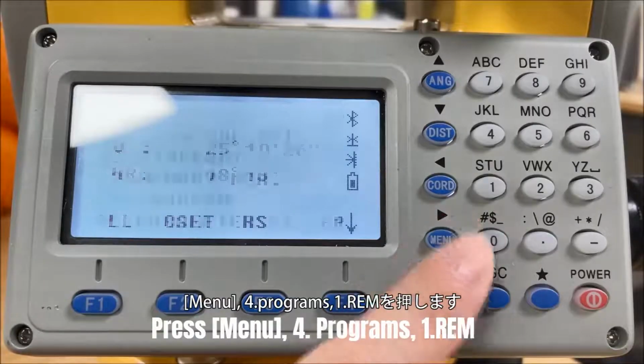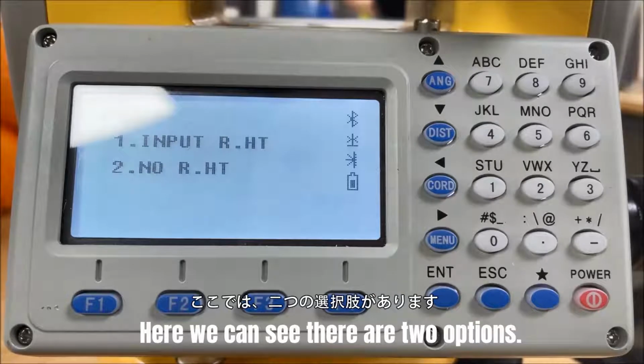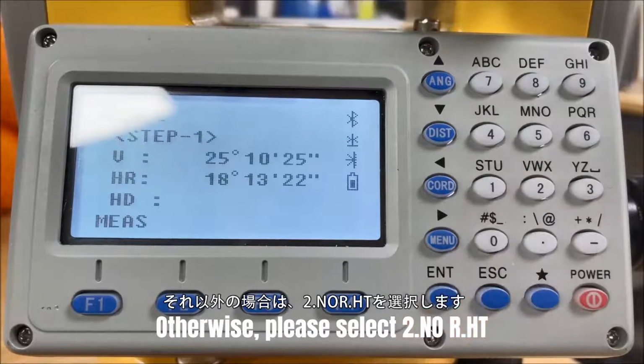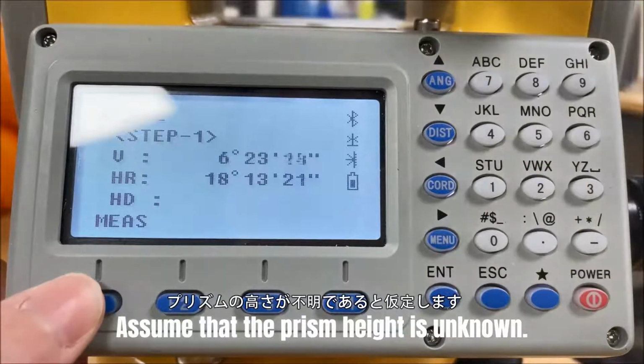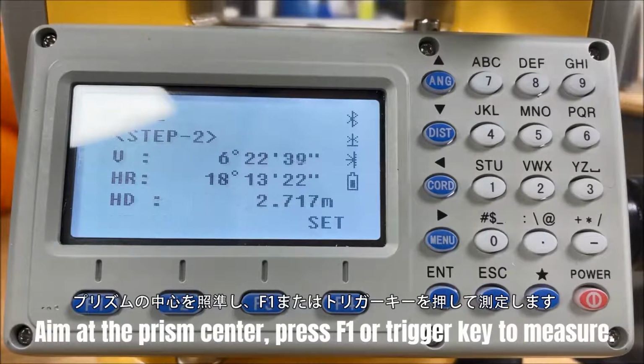Press menu, program and select the first one. Here we can see there are two options. If the prism height is known, we can select the first one. Otherwise, please select the second one to define the prism height. Assume that the prism height is unknown. Aim at the prism center and press F1 or the trigger key to measure.